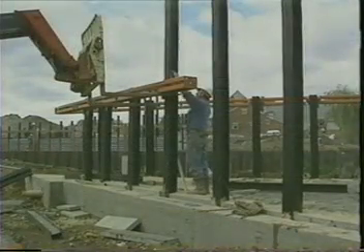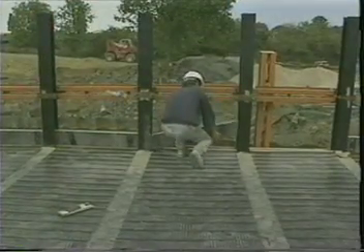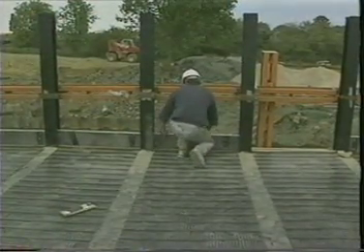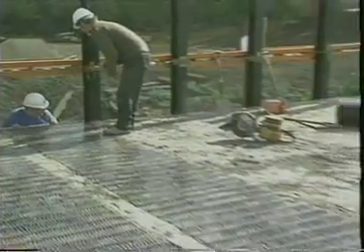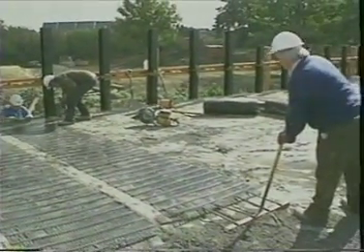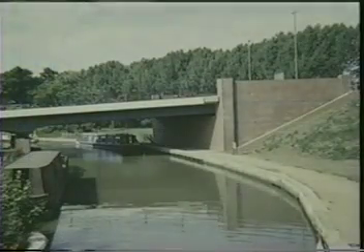Full-height steel posts are erected in the form of universal steel column sections. These are faced with precast concrete planking slotted into the webs. For this bridge abutment, the soil is reinforced with geogrids. These are gripped between successive lifts of planking as the fill is placed. Finally, a detached brick wall provides a pleasing finish.